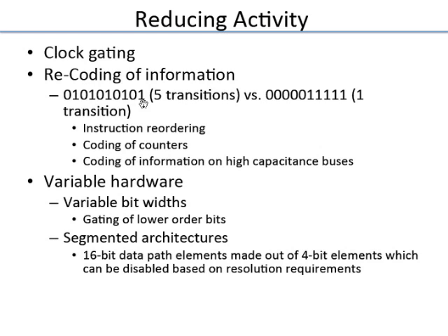If you see, there are 5 transitions here, 0 to 1 transitions. So the activity is half. In 10 cycles, 5 of them have 0 to 1 transitions. So activity alpha I is 0.5. Suppose you could reorder that, and you put all the zeros in the beginning, all the ones in the end. Then you just have 1 transition. Activity has come down to 1/10.